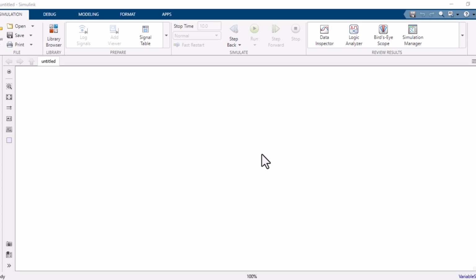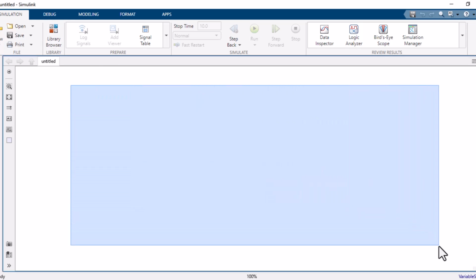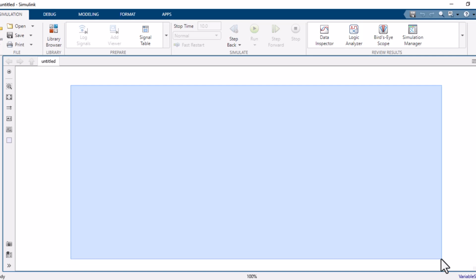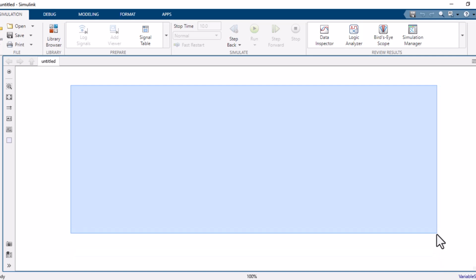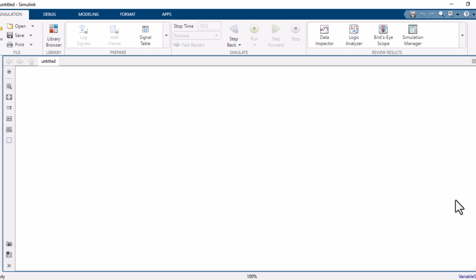What is a battery cutoff circuit? That means you are charging your battery pack, and once the battery reaches 90%, or maybe 80% or 70%, depending on the requirement, you have to plug off the charger. So that is the requirement of the model. The agenda of the model is to create the charging cutoff circuit.